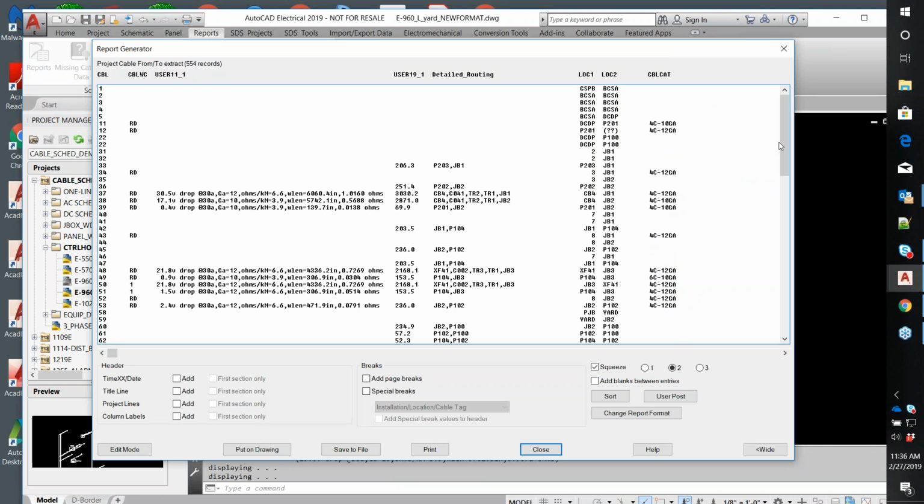All right, so it's added a column. Right here. This column is the calculated length of, for example, cable 37, which is going from circuit breaker 4 back to the marshalling cabinet, JB1. It tells me that it is 3,030 inches long, okay? We're in unit inches here in this drawing. So that's the length of the cable run plus the extra 10% that I asked it to add to the cable length for extra connection at the end.